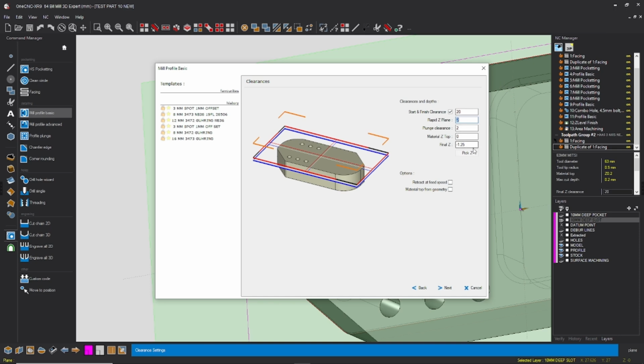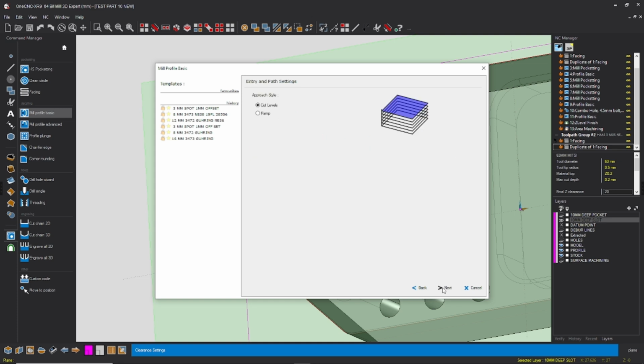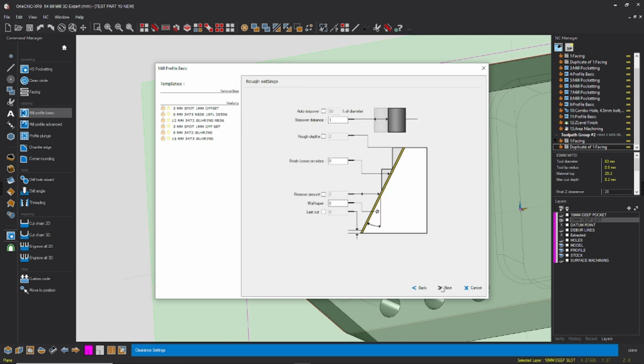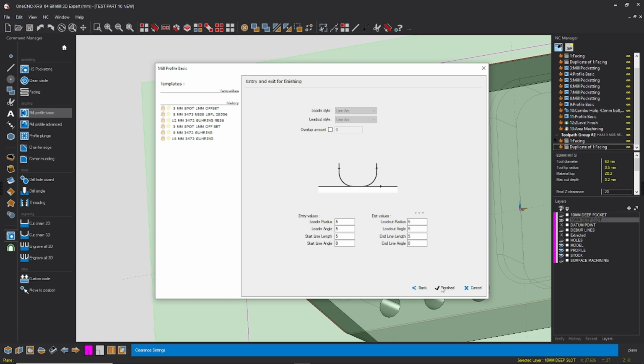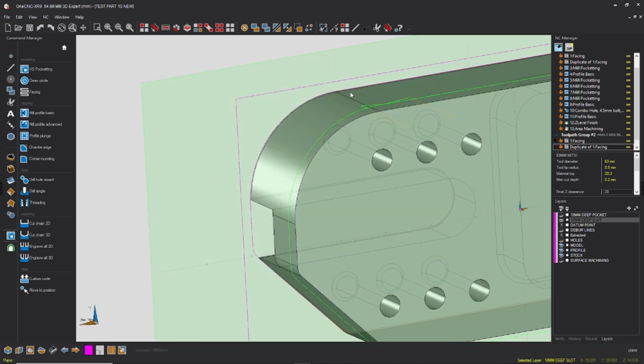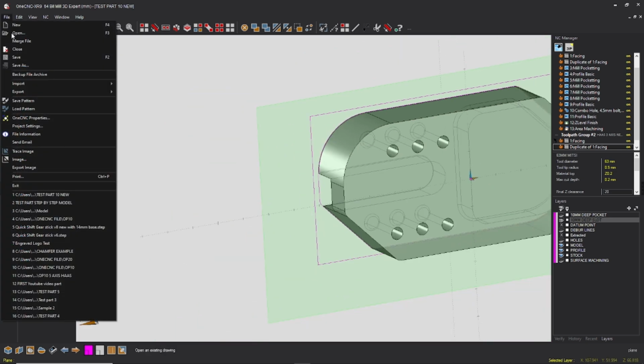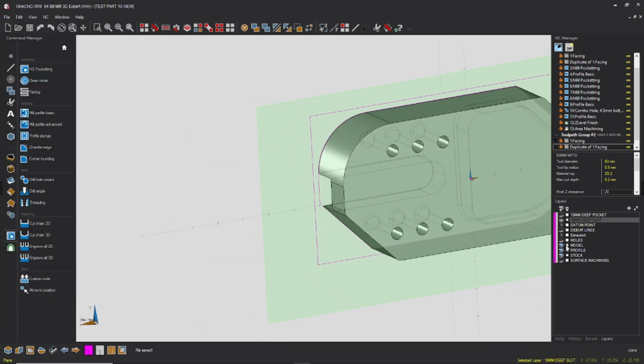I haven't modelled a chamfer here, so we'll do it as it says. We'll go 1mm deep, that's just a break edge. Yep, all looks good, that'll work. And you can see, even though I'm selecting these lines, it's putting them up here where my plane is set to. Click save, let's turn our holes on, let's turn the profile off, let's turn the stock off.